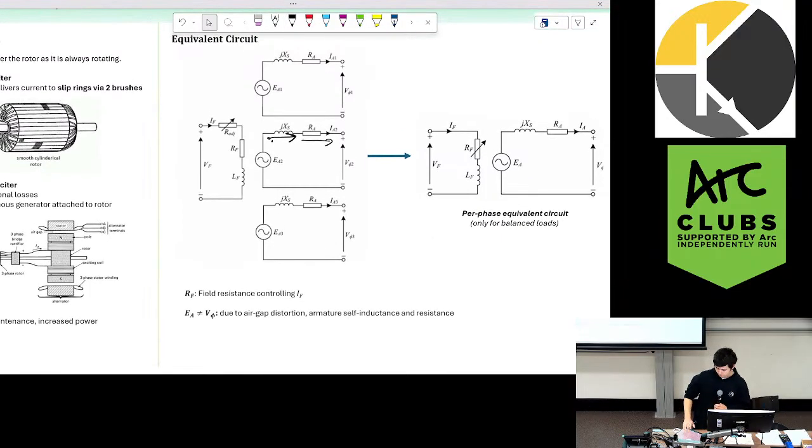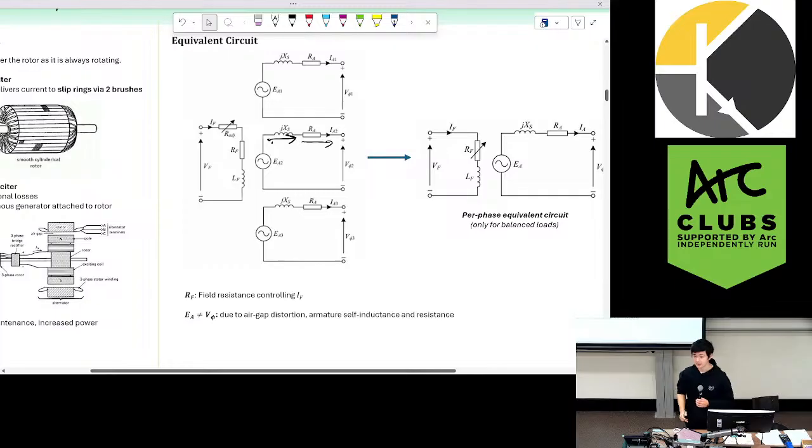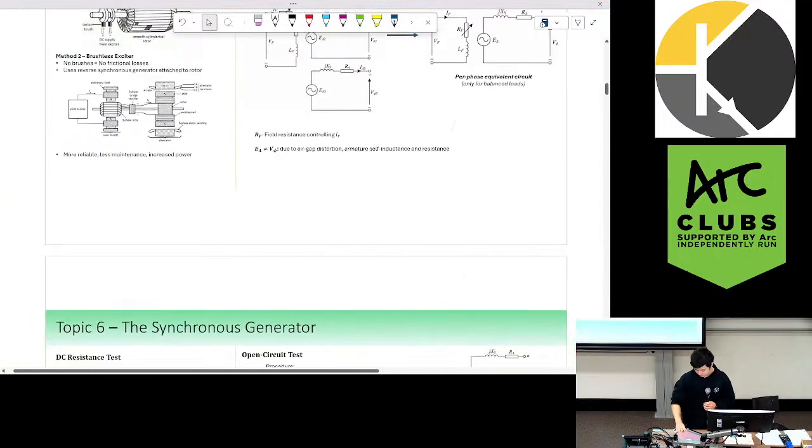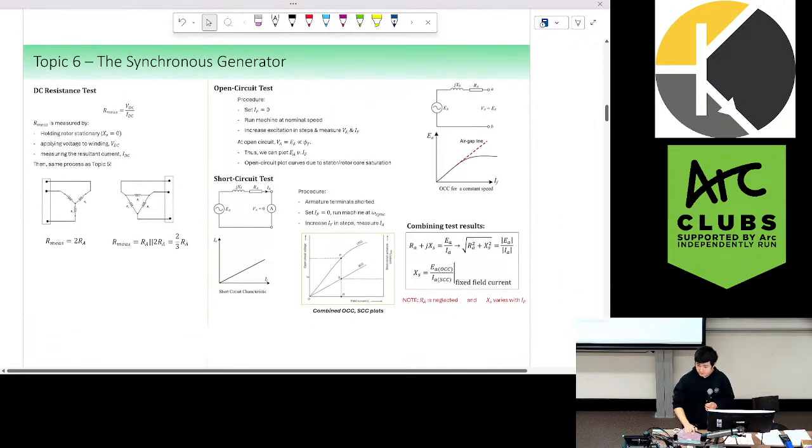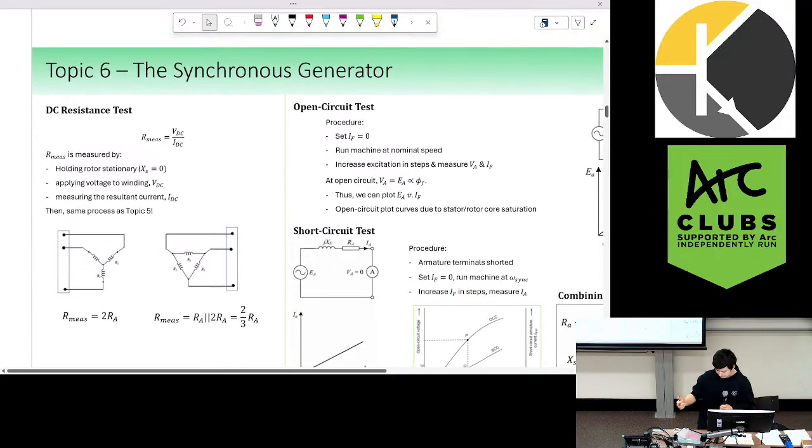Note that while we might actually be working at higher frequencies, typically the change in frequency does not have a significant skin effect. It might have some minute skin effect, which is just, okay, AC resistance is a little different to DC resistance, but that is the concept.